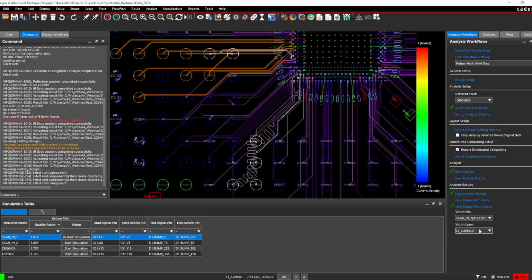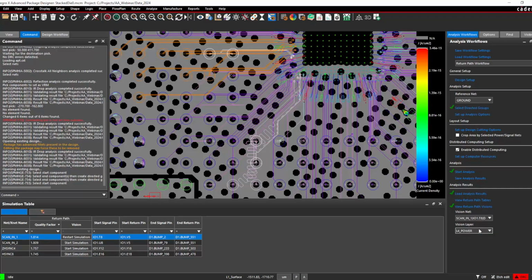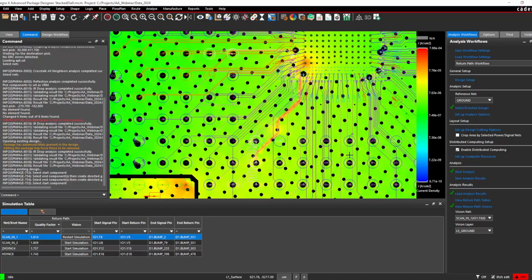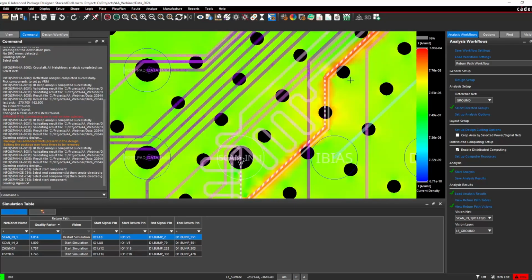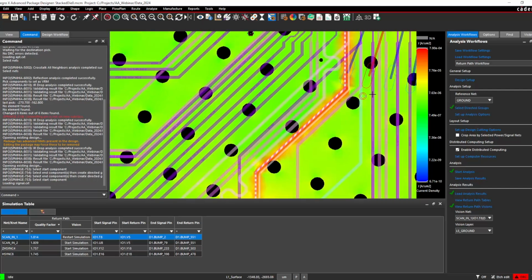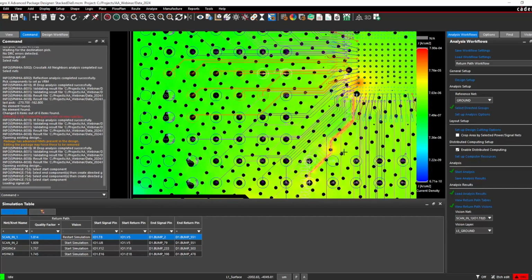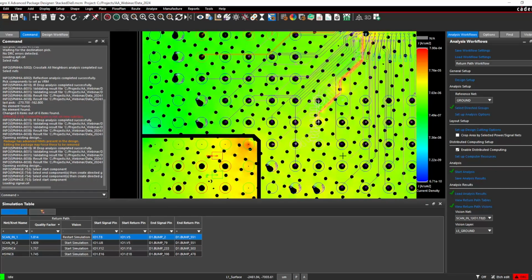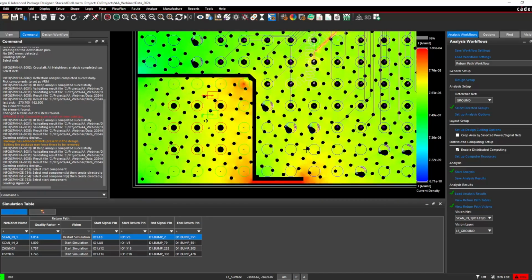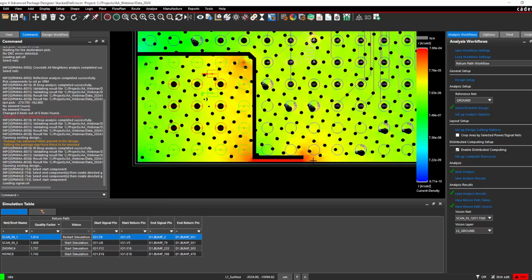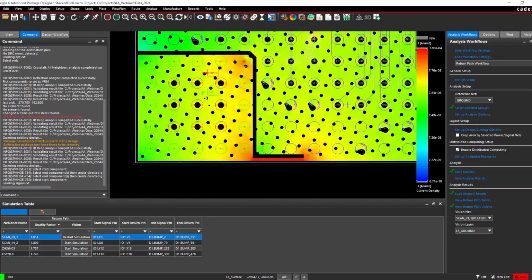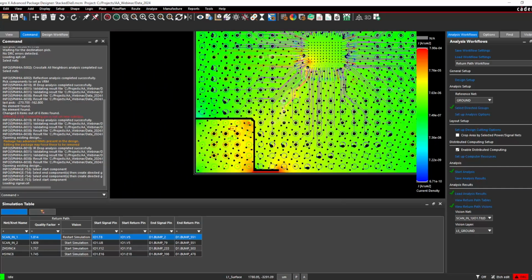So as we cycle through the layers, we run across the ground plane that is the reference for our selected net. And so we can see a graphical representation of the return path, but something sticks out as we zoom out a bit, and that is part of the return path. And we also see a bottlenecking because of this moded off area. And that is the cause of our quality factor issue. The closest ground pin for that signal net is behind the mode.